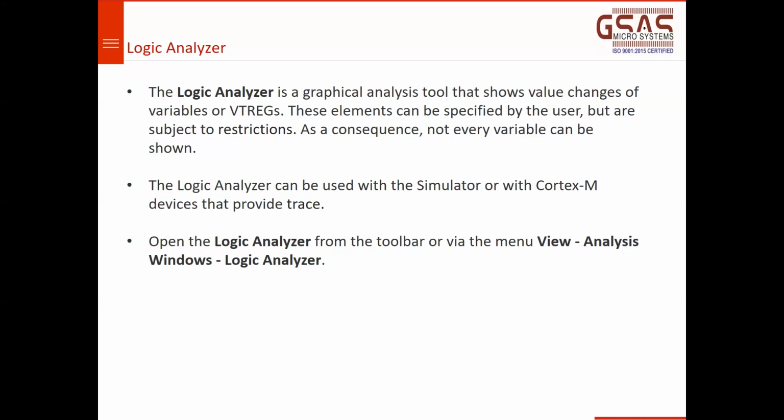So you see here the VTREGs. VTREGs are called virtual registers. As the name suggests, these registers are not present in the microcontroller. They are not part of the processor either. But ARM has given a set of virtual registers for each processor you select for the project development. When you create a project, you select a device, and based on the device you have selected, ARM gives a set of virtual registers. Using those virtual registers, we can write a signal function, and we can also simulate the interrupts.